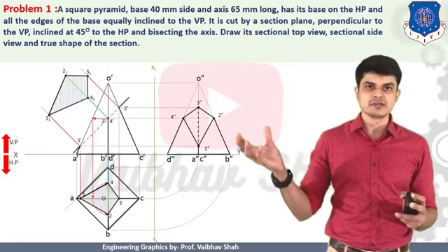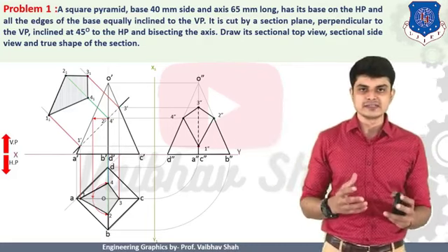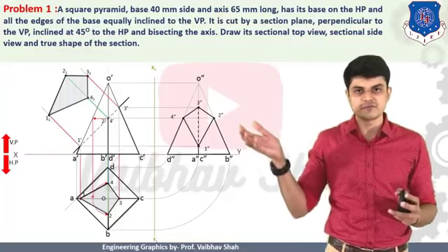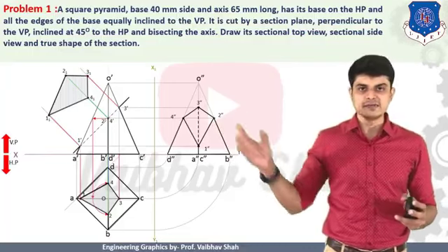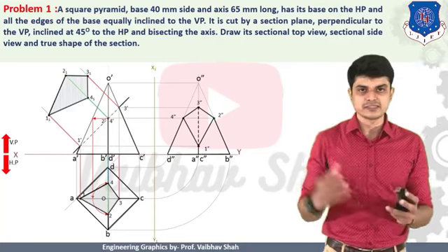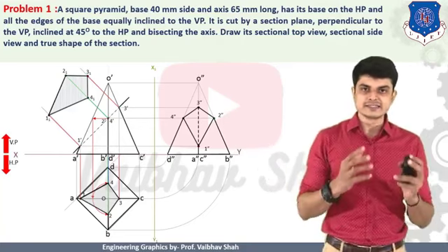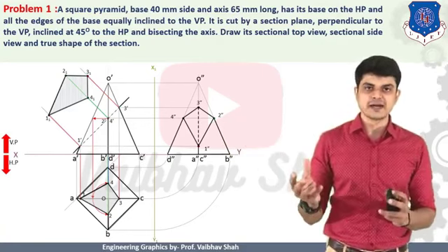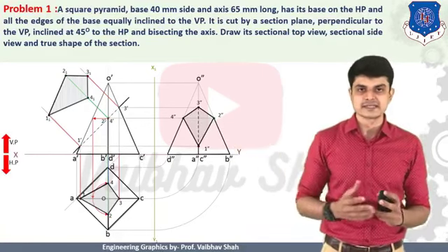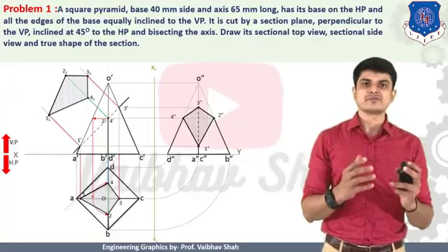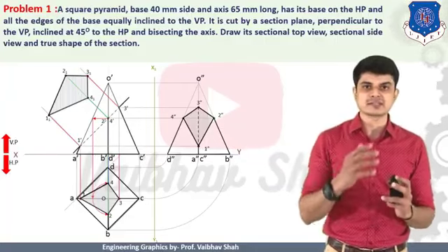Now then after, we should define the hidden line. As we can see, we are taking the side view from the left hand side direction of your front view, so the line 3C would not be visible in our case, so we should make this line a dotted line. And then after, as it is your cut section, you should specify the section cutting line on this section. So this is nothing but your section shown in your side view. That's why it is also known as your sectional side view.